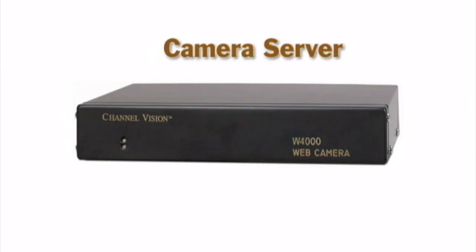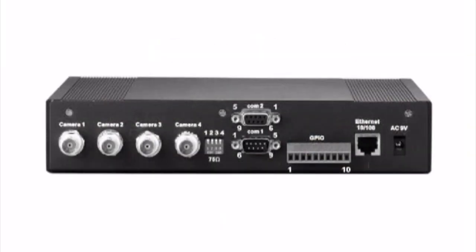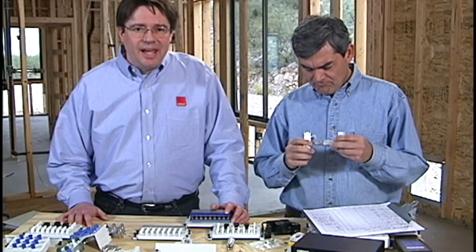This camera server takes the input from up to 4 cameras and converts the image to a web page with a pre-assigned URL, so it can be accessed from the in-home data network and from the internet. We'll connect its Ethernet port directly to one of the router switch ports. Next, we need to design and specify the RF broadband distribution system.